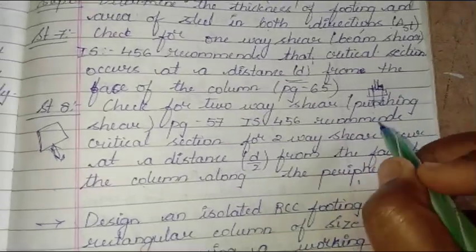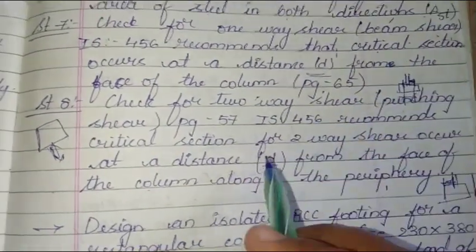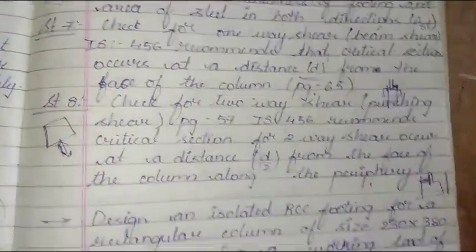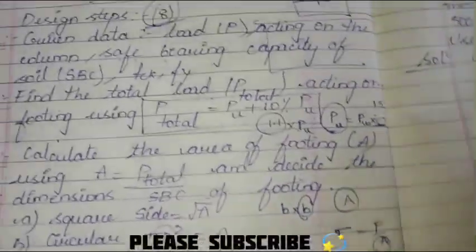Here, remember, it is at the distance D from face of column for one-way shear, and at a distance D by 2 from the face of the column along the periphery for two-way shear. So I'll be explaining you with figures once we get into this problem. Remember, just roughly I'm explaining you.